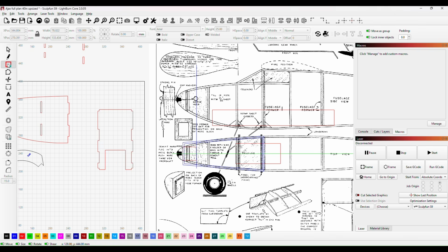So all I want to do now is probably just take a section out the top, because we don't want to be adding unnecessary weight. So if I make that 45mm wide, I can probably, if we maybe put a radius of 10mm on each of those corners, just like that.